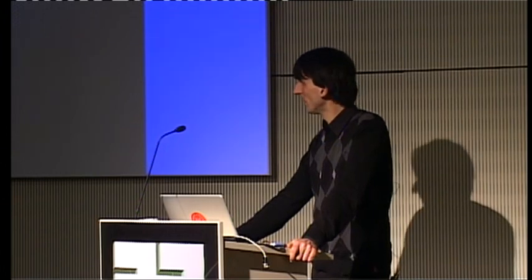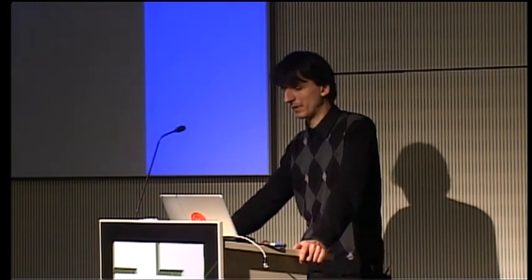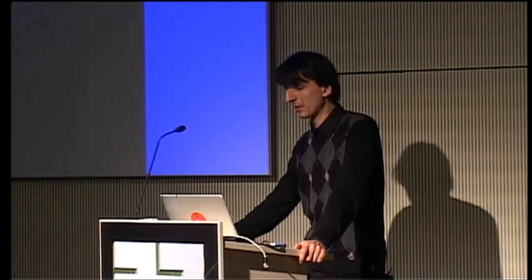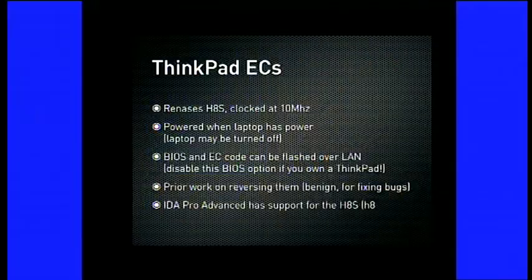Then you have Nuvoton, which uses a CR16 core, and they also have I think older ones that are 8051. And Fujitsu has this MB9378, which I have, however, only seen on Fujitsu and Fujitsu Siemens laptops thus far. And then, of course, the ones that this talk is about, namely the Renesas ones. So the Renesas ones are based on the Hitachi H8S architecture. So all of these are clocked at 10 megahertz.